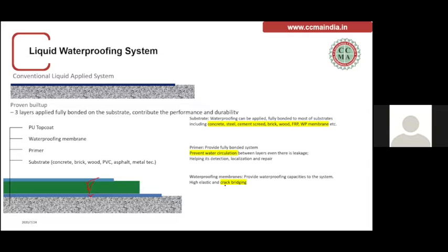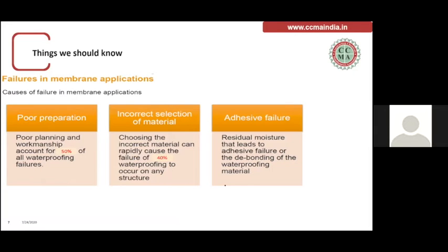The epoxy primer cannot bridge any cracks. It will just reduce the porosity of the concrete or the top layer. But when the waterproofing is applied, it will take care of cracks coming in the concrete. And then the top coats, we all know, are for UV protection.